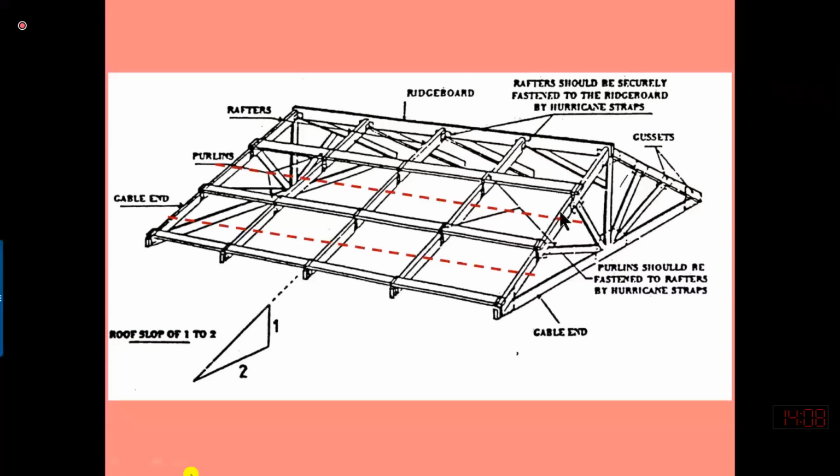If a line element is subjected to any transversal load, it is referred to as a beam. So in that case, we have to design the top chord member as a beam. But what we do at the start is keep the panel length less than the total width of roof sheeting available in the market. But if there is any case where we place the purlin on the top chord instead of at the panel point, we need to design the top chord as a beam.